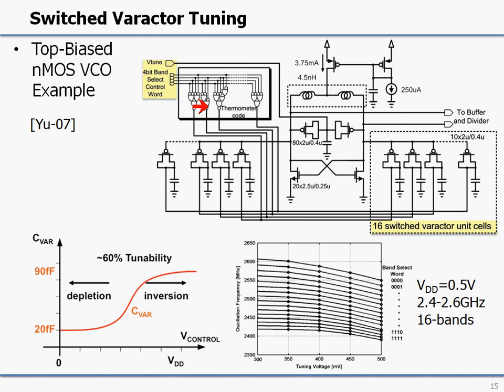So you put in a little bit of logic, and then you can build up these tuning characteristics in which you can discretely tune between these continuously tunable characteristics. In all these designs, it's important to make sure that your analog tuning varactor is sufficiently large that it can always cover the frequency step that you incur when you switch in a minimum unit cell in any of these switchable varactors, so that there are no holes in the output frequency.